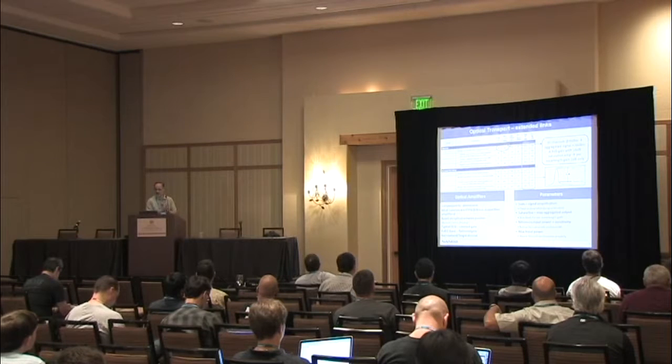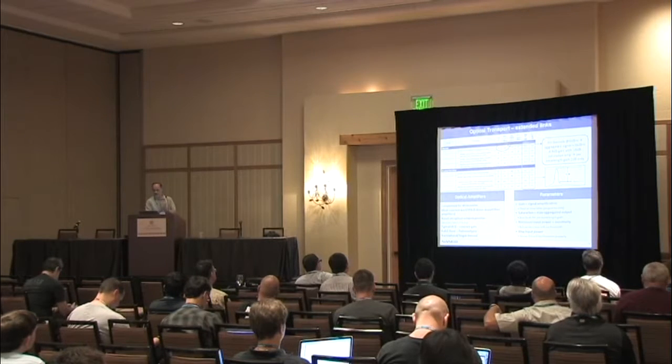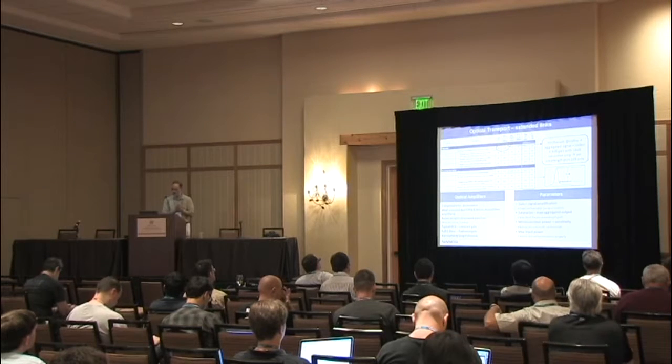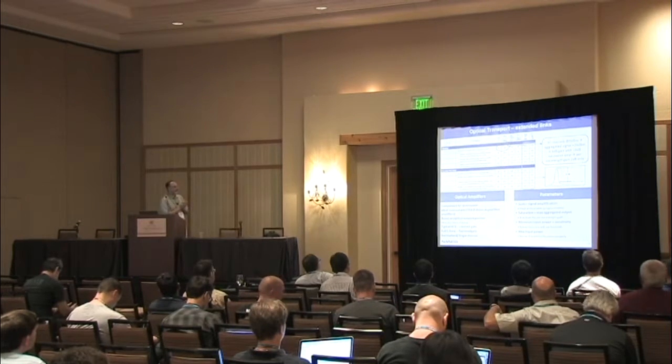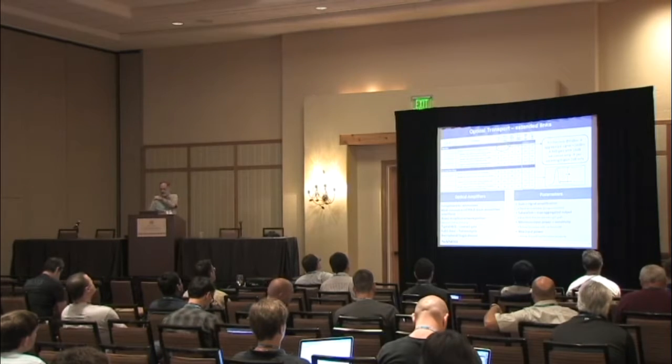with a higher maximum output. Minimum input, or the sensitivity: of course, below this value, the amplifier is not going to function properly. And maximum input: again, above this, the amplifier will not function properly. Another important parameter, less significant for the type of examples that we are going to go over, is the noise figure. Noise figure is basically the difference in dB between the signal level and the noise level, and the smaller the value, the better for an amplified network.